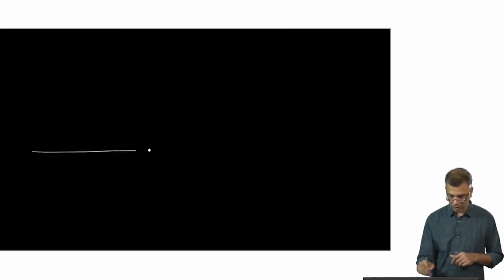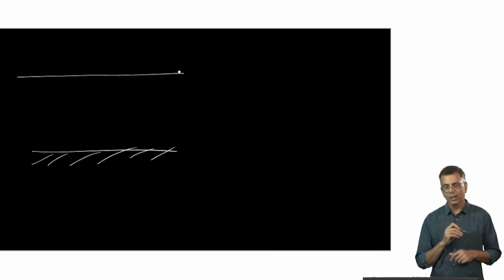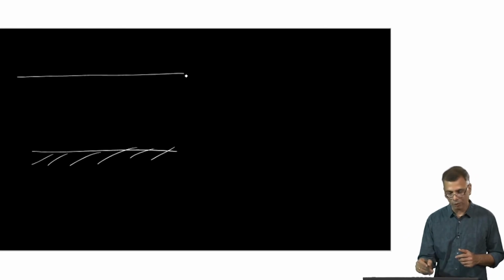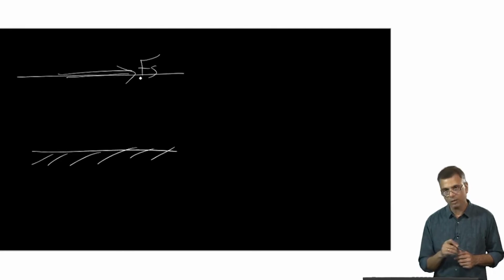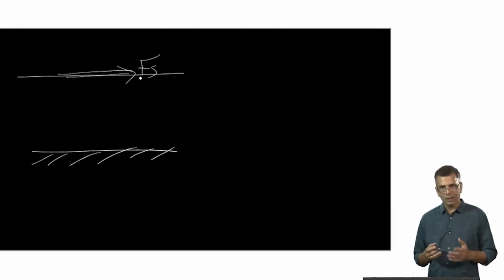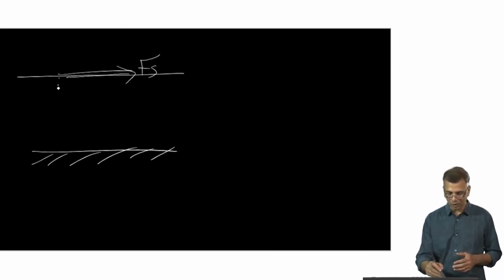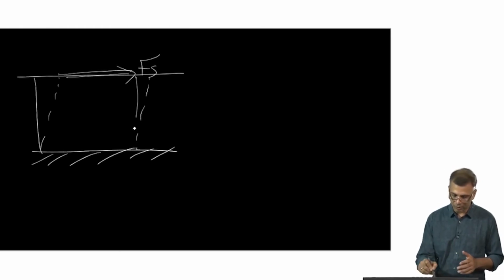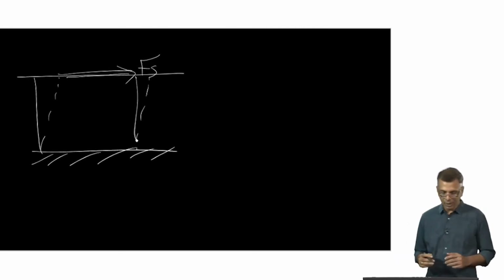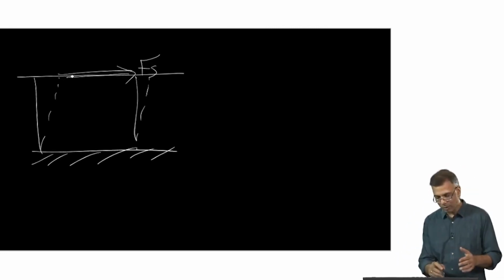And imagine a container of a fluid with a surface like this, either a solid or a fluid. This is how you differentiate: you apply a stress that's along the surface, in other words, a shear stress like this. Now a solid, as you would imagine, would be distorted, but not that much. It would distort a little bit like this, but it would tend to snap back to its original position, right? Whereas a fluid, on the other hand, will not be able to withstand this shear. It will flow.